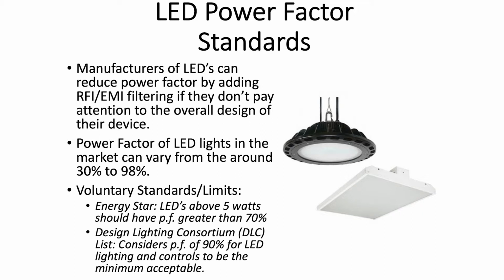Energy Star, the government program that everybody's probably familiar with, that labeling of equipment: LEDs above 5 watts should have a power factor greater than 70%. So the government says, okay, we're going to call Energy Star power factor above 70% to qualify. The DLC list, as I said, considers 90% and above as the minimum acceptable. So even Energy Star is quite a bit lower than the DLC criteria that Hoosier essentially requires you to buy from to get your rebate.